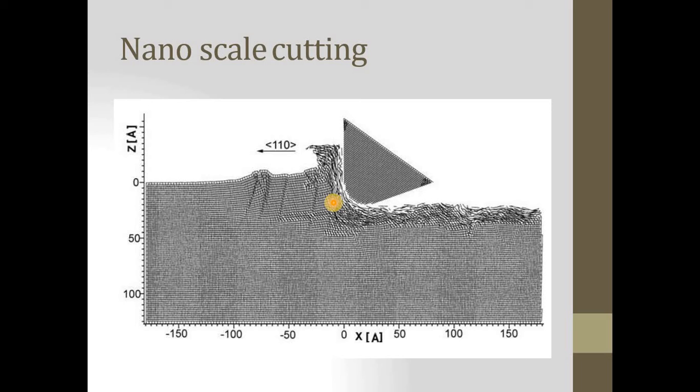than before. Analyzing the changes in the microstructure depends upon understanding the involved mechanism of material removal for specific cutting conditions. In the figure, the different areas of crystal orientation are separated by lines, and slip lines are drawn with identical dislocations.